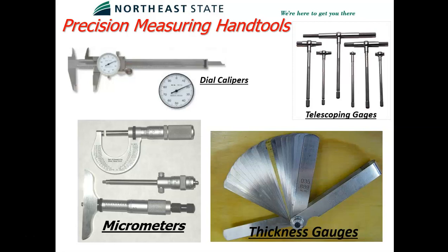So the dial caliper is a tool that's probably just about as expensive to buy one dial caliper as the micrometer, but the dial caliper can measure a much wider range than the outside micrometers.